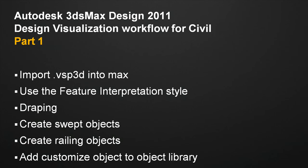In the first part of our design visualization workflow for Civil using 3ds Max Design 2011 and the Civil Visualization extension, we'll have a look at how we import the .vsp3d using the feature interpretation style. We'll have a look at how we can drape the image on top of a terrain, create sweep objects such as bridges, create railing objects such as guardrail and railways, and we'll also add a customized object to the object library.